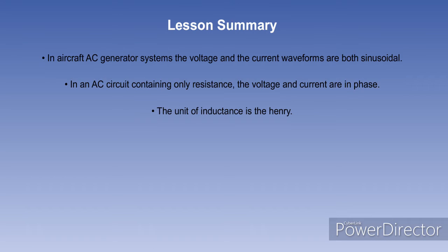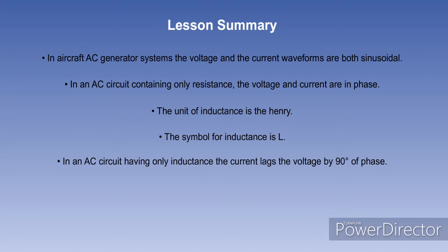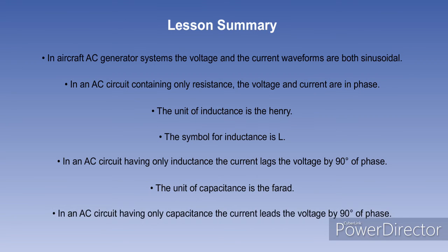The unit of inductance is the Henry. The symbol for inductance is a capital L. In an AC circuit having only inductance, the current lags the voltage by 90 degrees of phase. The unit of capacitance is the farad. In an AC circuit having only capacitance, the current leads the voltage by 90 degrees of phase.